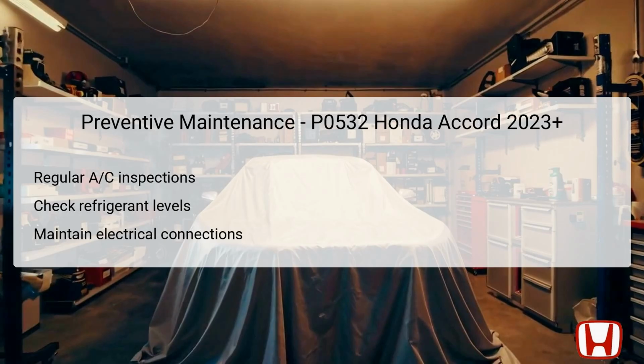Engaging in preventive maintenance for the AC system can help avert future occurrences of DTC P0532 and maintain optimal performance. Schedule regular AC inspections to catch any potential issues early on, ensuring that the system operates at its fullest capacity. Additionally, check refrigerant levels in the system to confirm they are within the manufacturer's specifications, as improper levels can affect performance